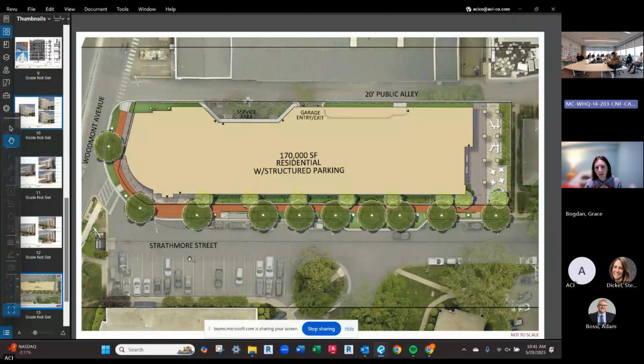I think maybe you want to say not specifically Nichiha, but cementitious panel, so that you have more options. A generic panel system. Yeah. I think you can do it. Not tied to a specific manufacturer. Fewer joints, cleaner. It's going to be challenging. Give us time to explore. Some of these panels come with a size, that's what you're seeing, size limitations.